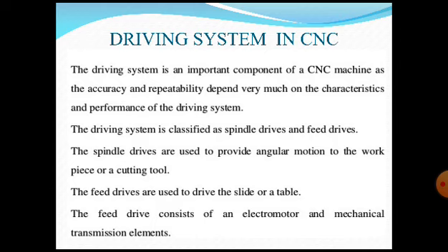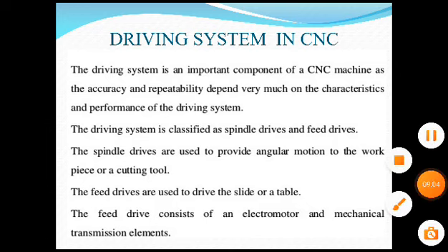The feed drives are used to drive the slide or the table. Basically the main function of the feed drives, that is the feed motors, is to drive the slide or a table. That means it is used for giving the motion to the table or the slide accurately. Even the guideways, whatever are there, are placed correctly in the accurate positioning depending upon where the workpiece has to be machined. The feed drive consists of an electromotor and mechanical transmission system. We need to understand one important concept here. Whenever we are going to provide the motion to the table, then we need to understand